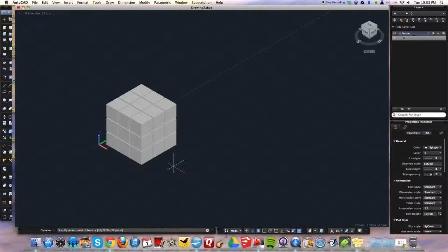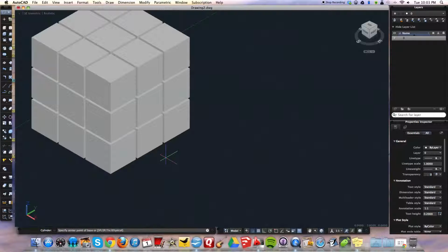I'm just going to make one beside this. Because this square is not centered on the grid, I'm going to turn the snap mode grid off, and I'm going to turn on this other thing here that says infer constraints, because I'm going to show you what that does in a minute. And I'm going to turn on object snap. Okay, I'm going to start on the midpoint of the middle one, and we're actually going to build this thing out to the side and then move it in. I'm going to start there and hover for a second and then move.